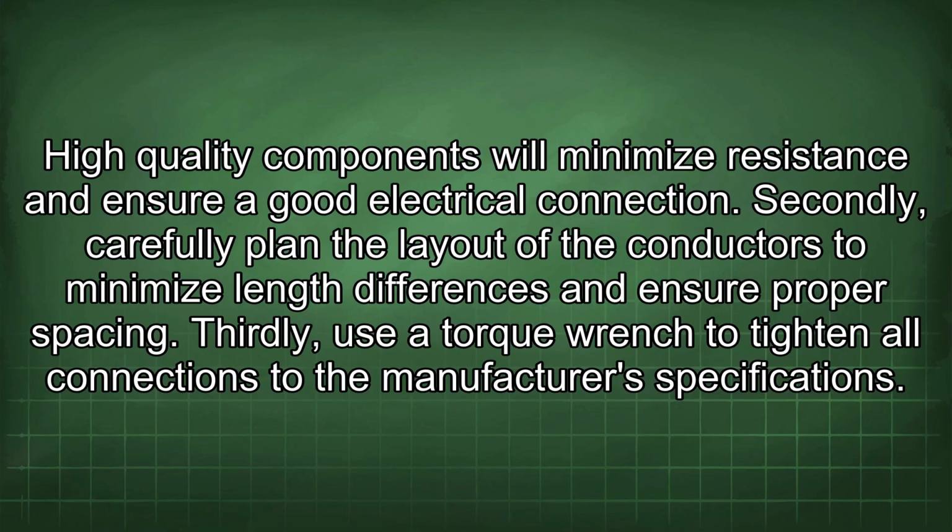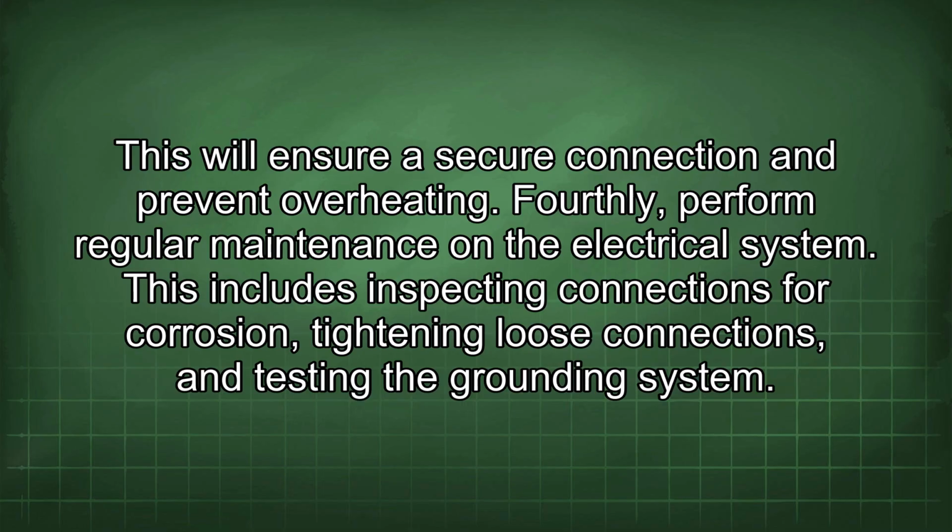Thirdly, use a torque wrench to tighten all connections to the manufacturer's specifications. This will ensure a secure connection and prevent overheating. Fourthly, perform regular maintenance on the electrical system. This includes inspecting connections for corrosion, tightening loose connections, and testing the grounding system.